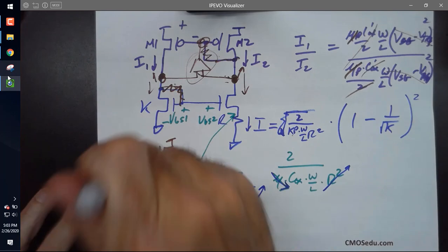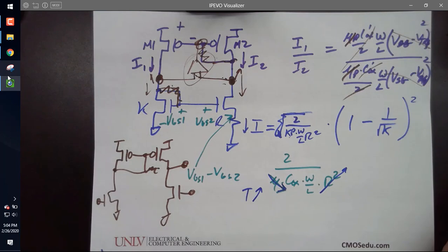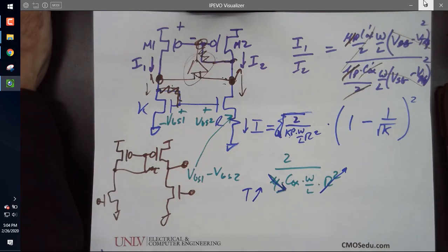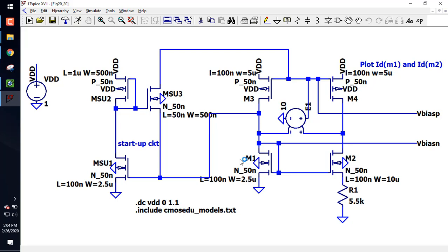So I'm going to do this first. Instead of using transistors, I'm going to just simulate it with the voltage controlled voltage source. Let me go over to, it's probably like this figure right here. And I'm going to look at this point, and then, instead of gate drain connecting this, I'm going to connect the output of the amplifier to the voltage controlled voltage source. Everybody see that? Okay, so now, first question. I need to have negative feedback or else I'm going to have like a screeching amplifier, right?